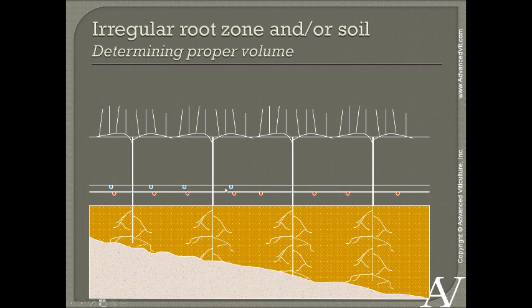so that we can irrigate that area earlier. So we'll start off with this zone, irrigate these vines, and these vines are going to still have moisture, so we don't need to irrigate them yet. And eventually these vines are going to catch up with these vines, and these will start slowing down their growth, and we'll be able to irrigate both of them, and then we can go back to this main drip line, which has all the emitters. This is also useful when we have interplants, replants, other just practical considerations.